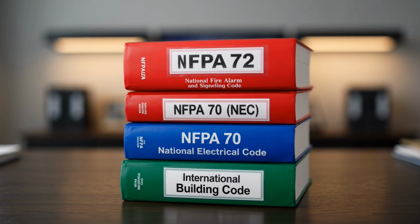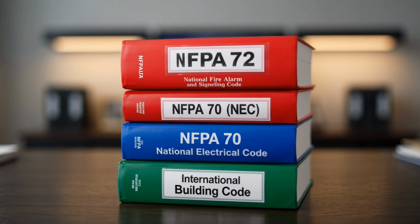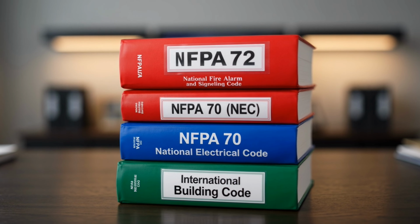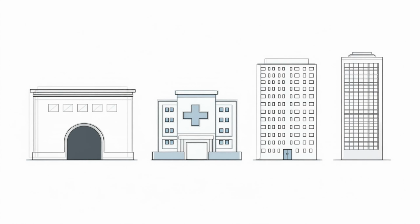All design begins with the rulebook. NFPA 72 is your fire alarm Bible. NFPA 70, the National Electrical Code, governs wiring. Always check the local building code for amendments. Design requirements vary drastically by how a building is used. A theater, a hospital, an apartment, and an office each have unique detector, alarm, and placement needs.